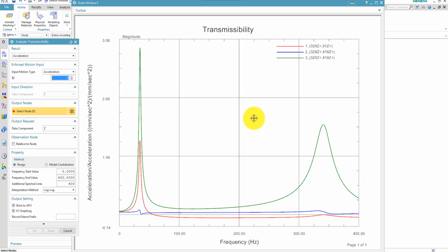And then you could select which nodes you think are of interest, and those nodes are probably nodes where you have some kind of delicate instruments. And the input nodes are where you have the load from excitations, obviously. In this example, you should probably check if any other modes in this frequency range influence, because node number 3 was on the corner node of the bracket, and it might be that mode number 2 should have been included in this simulation. Please try.